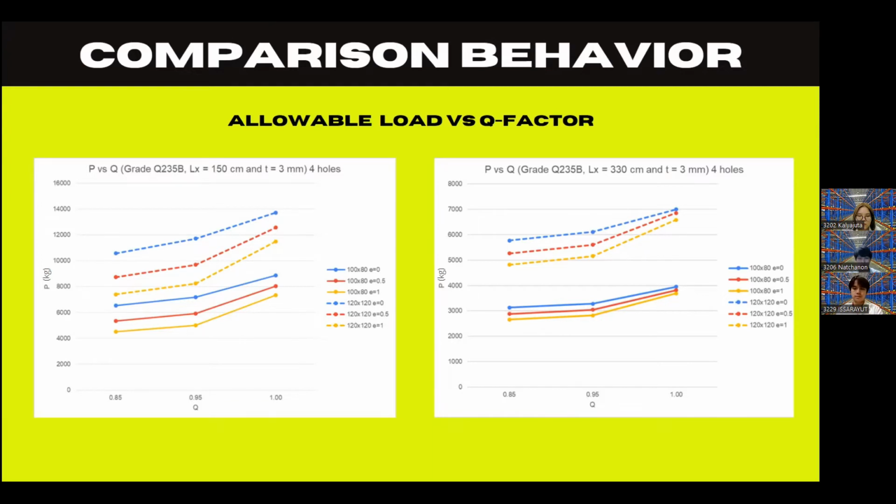However, load with eccentricity makes a moment on columns, which makes allowable load decrease as curved lines, which can be seen in eccentricity at 0.5 cm and 1 cm. So eccentricity has a high effect on columns, which decreases the load capacity highly when the sections are perforated.